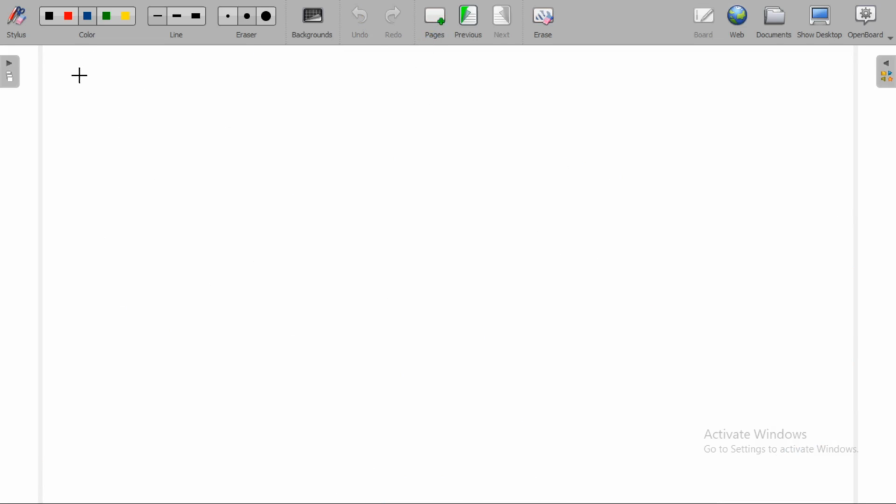So what is R1 now? R1 is equal to omega square R2 R3 R4 C4 square by 1 plus omega square C4 square R4 square. What about L1?